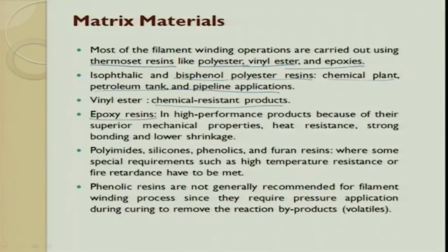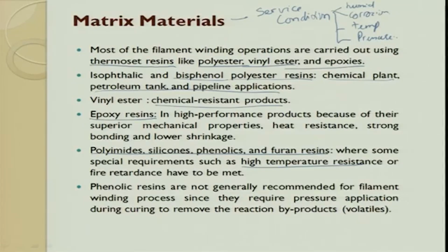So generally we use epoxy, then polyimides, silicones, phenolics and other resins also we use for high temperature. So depending upon your requirements, depending upon your service condition. What is service condition? Here one is humidity or water content, next is corrosion, next one is temperature, the next one is pressure. For example, today windmills, the base stand or the stem, is now made out of composites, and they are also trying to make this with the filament winding process.